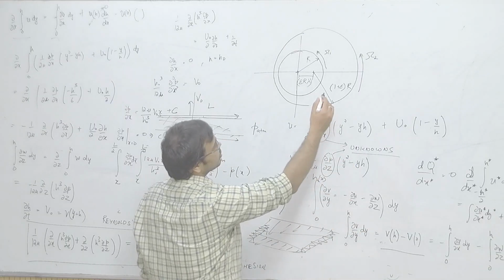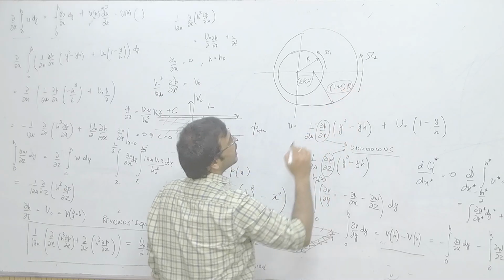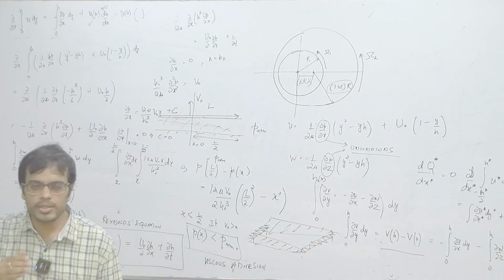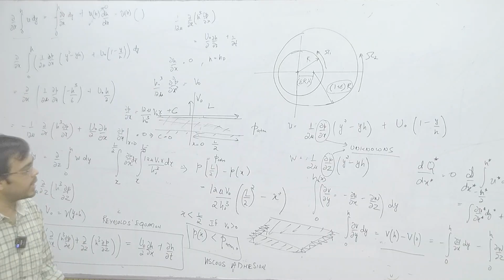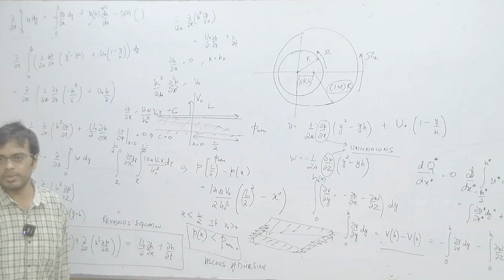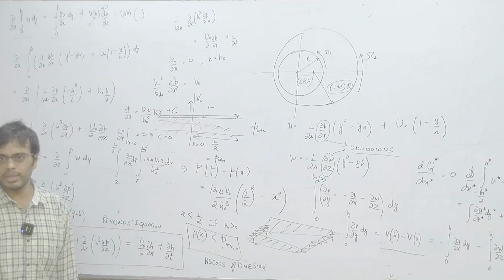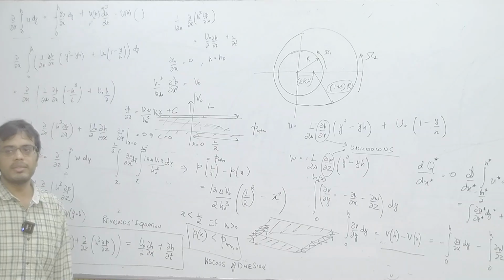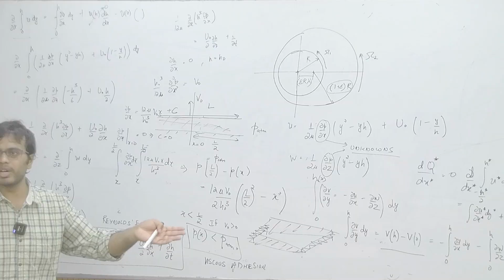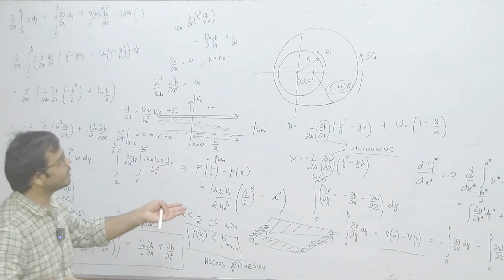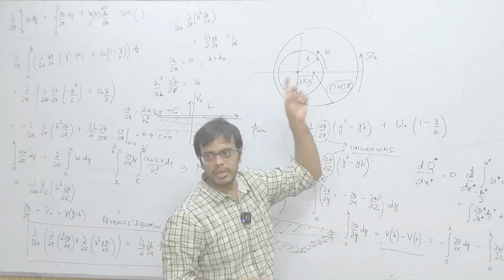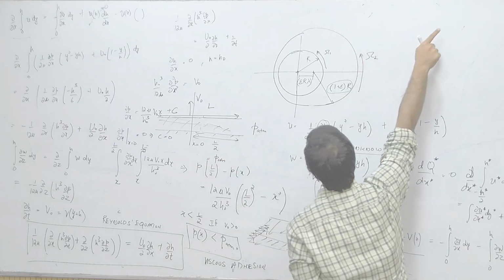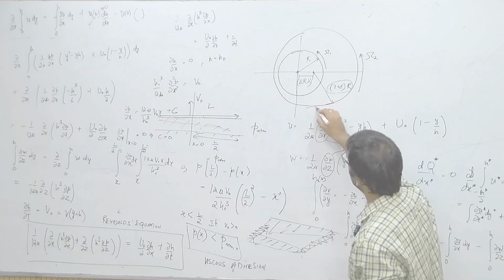Okay. And so, notice that I have a 1 plus epsilon r. So, the radius of the outer cylinder is just slightly higher than the radius of the inner cylinder. So, the gap between them is small, and you can expect that all the lubrication approximations that we have covered just now, when the transverse length is much smaller than the streamwise length, will hold. So, you can apply the Navier-Stokes equations in cylindrical coordinates.